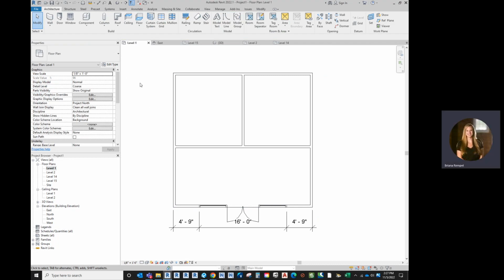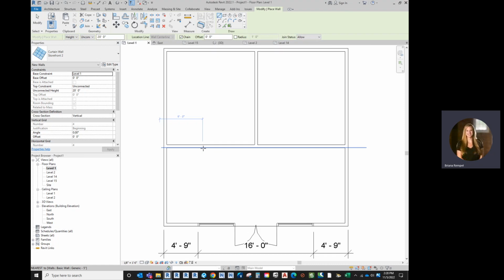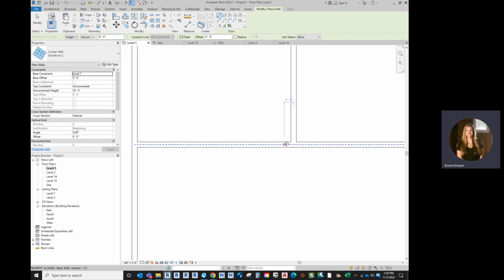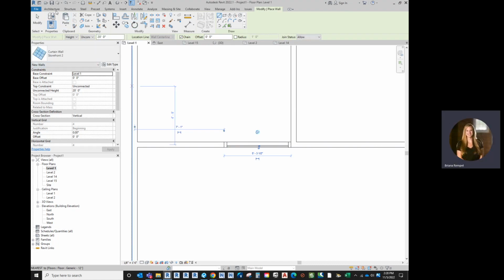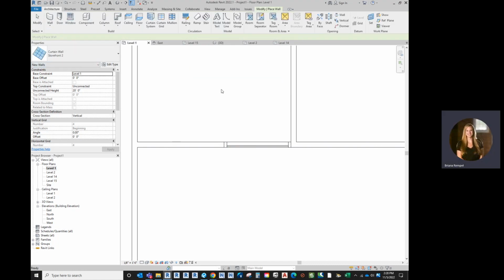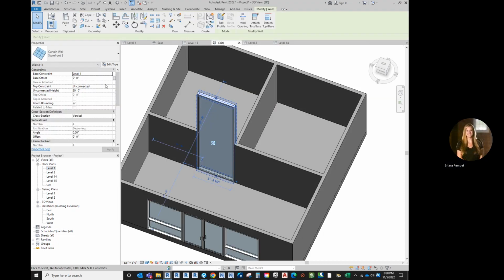Okay, so let's use this as if we have a door and a side light for an interior office. I'm gonna make sure that I use my storefront 2 that doesn't have any preset grids so that I can work with what's going on there. Let's say maybe we have 5 foot here. And then I go back to my architecture tab. Oops, can look at it in 3D. It's just one panel right now. I'm gonna knock it down to 8 feet again.